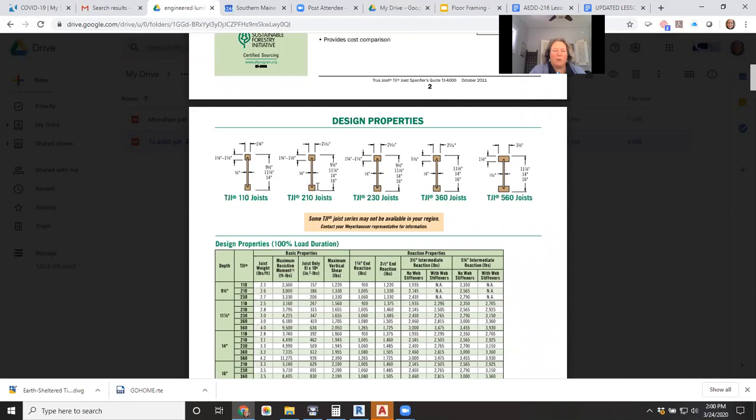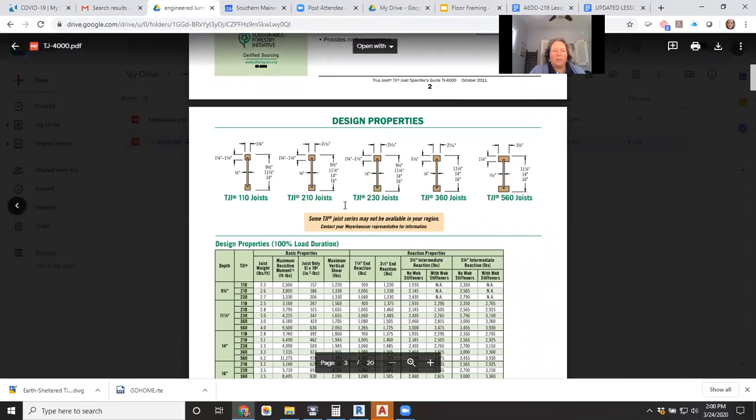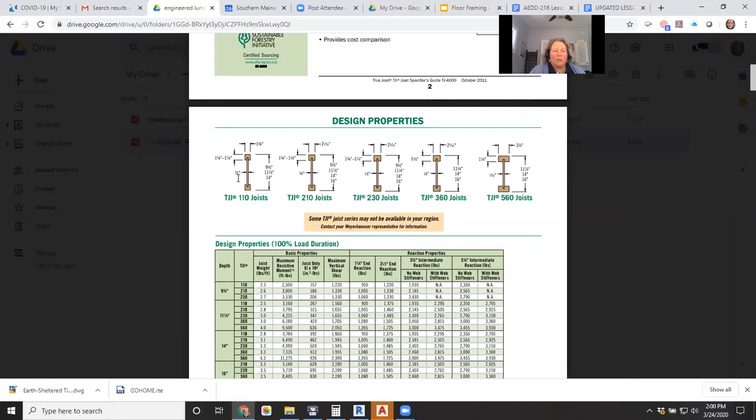These sizes that you see below are the different nominal sizes for each one of these I-joist types, and they usually result in the size of the web or the flange being wider or thicker in order to span longer distances. So this is going to be the thickest web and the widest flange here on the end, these TJI 560 joists, and they come in these depths. 16 inches is the deepest floor joist.